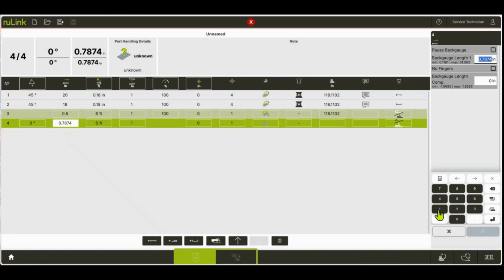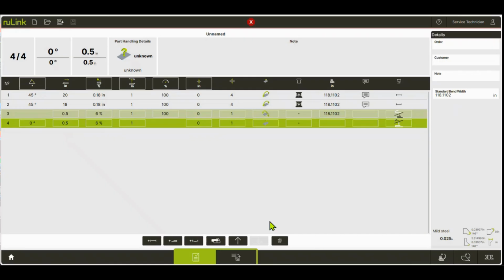I'm going to tell them I want them to be at 0.5 because I got pretty much a 1/2 inch hem anyway on the inside of the machine. And this is the clamp pressure. This is the open height afterwards. We don't need to know the bending beam speed again right now because it's not going to be using the bending beam. It's just going to be smashing, right?